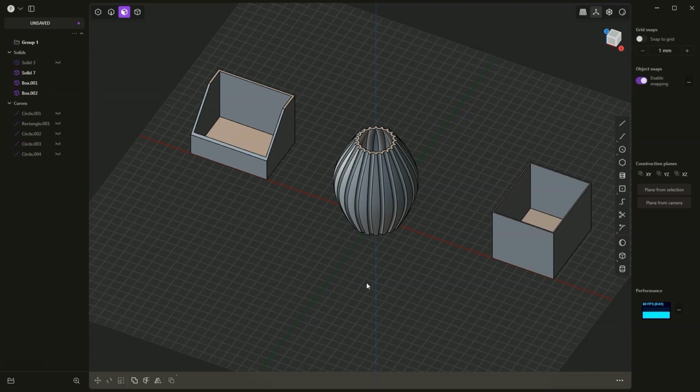We don't have to combine it by, for example, creating two elements and then subtracting one element from the other to achieve an element with thin walls. We can simply use the hollow solid command, and by combining this command with, for example, the loft command, we can get quite interesting shapes. We will finish this lesson and move on to the next lesson.